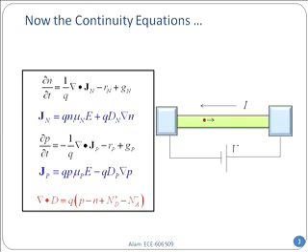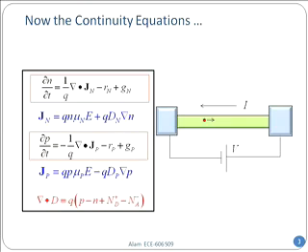Now, before I move on, let me point out something important. If you look at the 5th equation, this is called the Poisson equation. The Poisson equation relates the charge to the electric field, or here the displacement D is related to the electric field with the dielectric constant multiplied by the electric field. Now, when devices become very small, molecular devices, not the big transistors that we talk about, the Poisson equation might get modified.